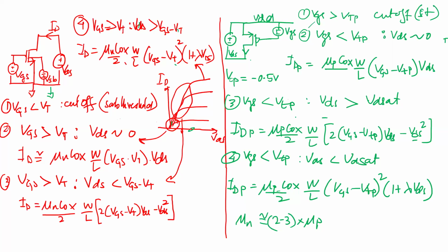So there are various ways to reduce that. One brute force method is you just make the channel area really large. If you make that large, that average just reduces. The other techniques are circuit techniques where you actually switch the devices fast so that all the low frequency noise gets canceled between two devices. That's called chopping. Okay. But PMOS is the reason PMOS is involved.